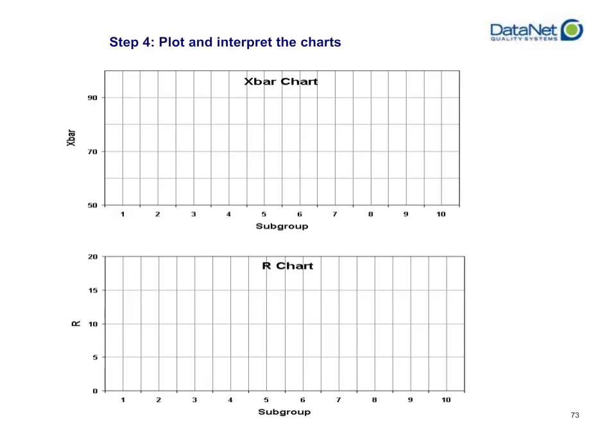Something to note, to take care with when you're doing this by hand: you probably want to use a ruler, you probably want to use a pencil, and very important, make sure your scaling makes sense, because if your scaling is off, it's going to be really hard for you to draw each one of your data points. So take care to make sure that your drawings are actually going to fit in the charts that you have available to you, and that the scaling is consistent. We did provide to you in the SPC Fundamentals training manual a set of charts that give you pretty good scaling already, but do take care not to squish the data too tightly.